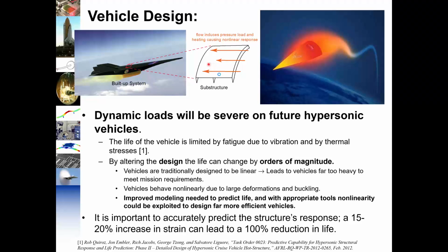And again, the nonlinearity we're interested in is basically what happens if you imagine this panel deforming with large amplitude: you can get a bending stress turning into an axial stress. So at small amplitude, it's mostly the bending stiffness that dominates. At large amplitude, you have to stretch the panel to be able to deform it more. And so the stiffness goes up a lot.